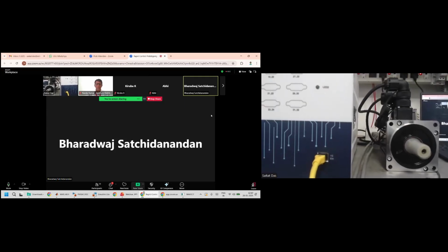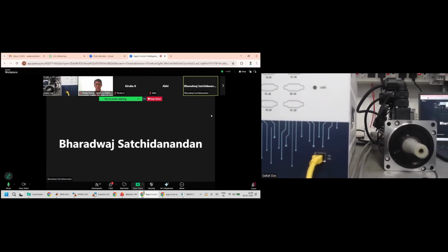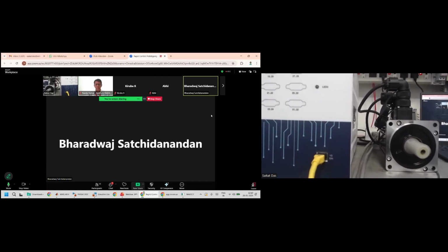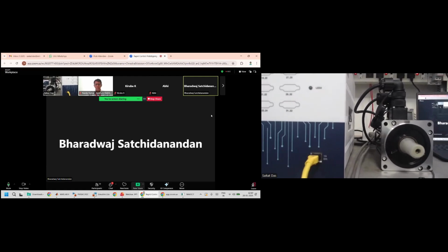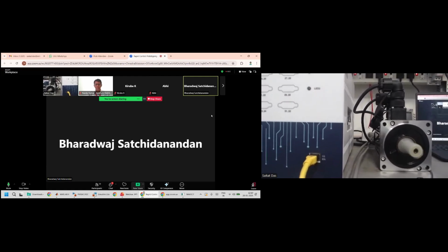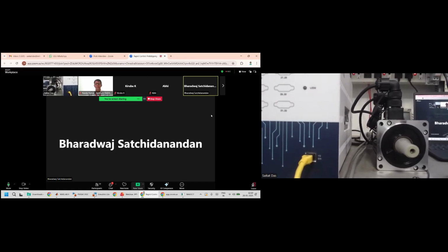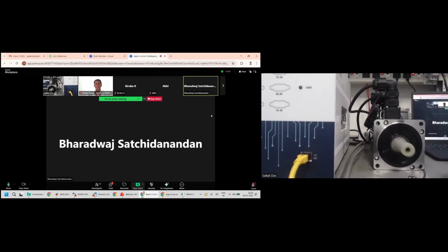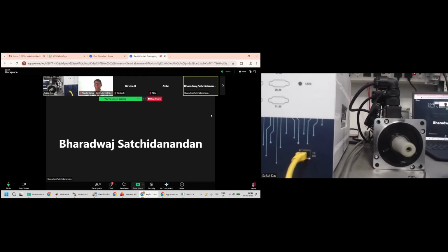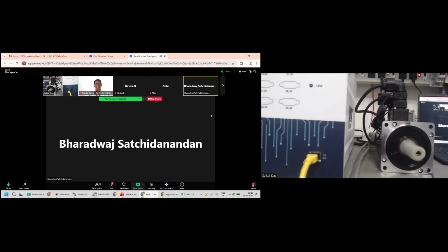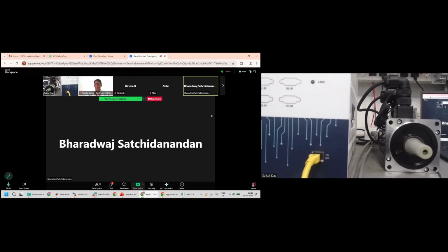Yes, definitely, sir. This controller is definitely customizable for those applications also. As of now, for the control logic development, we are using the standard MATLAB Simulink workflow. If you are using, let's say, some drone control block sets inside MATLAB, by using the control libraries provided by MATLAB, and those block sets are able to generate compatible C code, this controller is capable, sir, for rapid control prototyping.